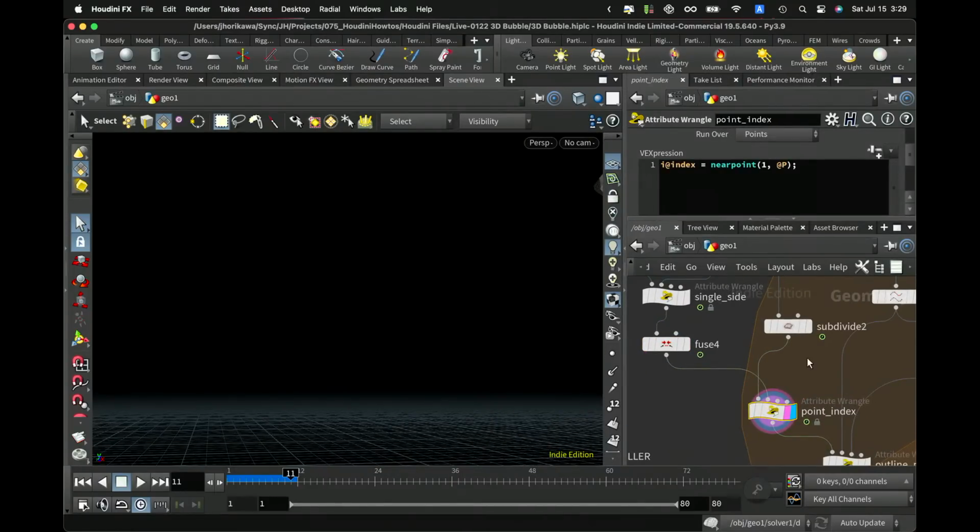So it might make sense to first get the nearest point number, get the point position, calculate the distance, and if the distance is small enough to 0, then you could use the index NPT. If not, then set the index to -1.